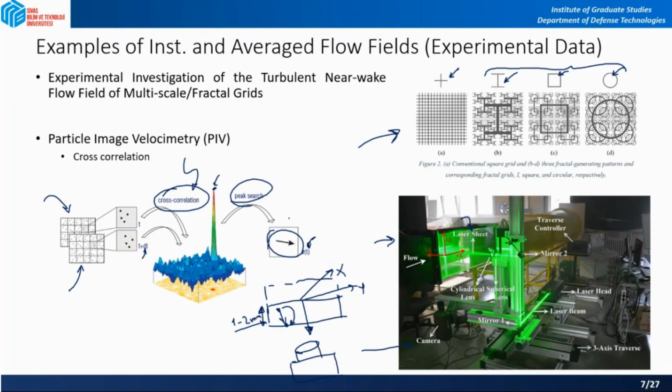And the x and y components of velocity will again be known to me. So this is, let's say, u, and this is small v, the x and y components. So by two consecutive shots, separated by a very small time dt, I was able to get the displacement information of the particle at that instant of time.